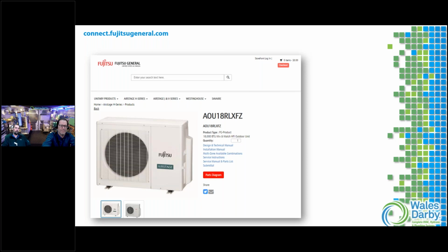So based off of that load calculation, now we can start looking at the equipment. Once you do that load calculation, don't go right to the catalog. I think that's where a lot of people shoot themselves in the foot. They go to the catalog, see I need X amount of BTUs for this space, this one model can do up to that, great, that's my piece of equipment. Then maybe down the road we have some comfort complaints, because we looked at a number and we weren't aware of what that outdoor temperature was when we were getting those BTUs out of the machine.